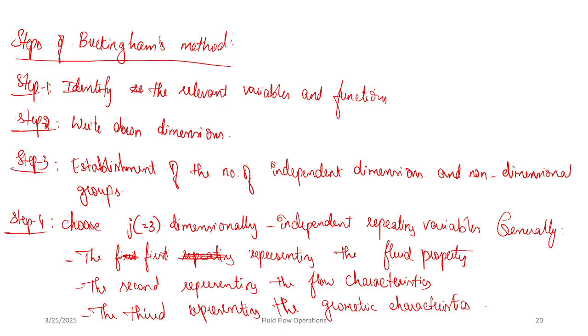And also, we should not be choosing density terms like density, gravity, and specific weight as repeating variables. Okay.